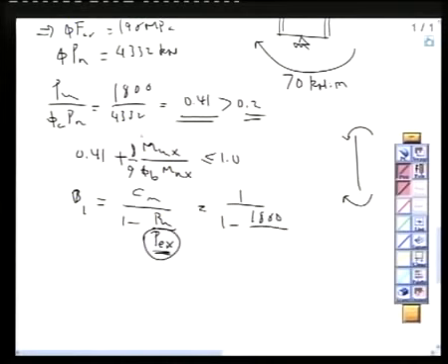So to calculate BEX, it will be pi squared EA divided by KL over R of X all squared.